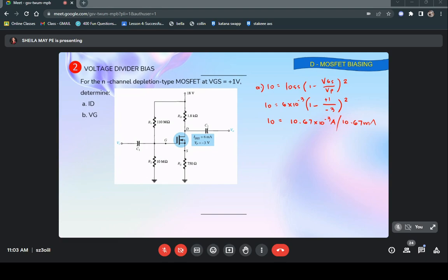Okay, in here, we have a voltage divider bias. So VG, the same formula as in class. VGS is just VG minus VS. This is VS, that's the voltage drop across our source resistor. So VGS is just equal to this because VS is IDRS. And VDS is the same formula as for our D MOSFET and JFET rather, the same formula as in class. We're adding the voltage divider bias.